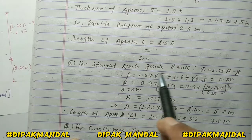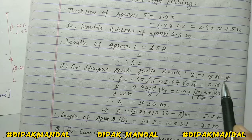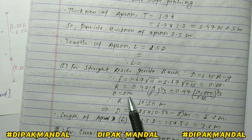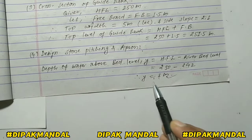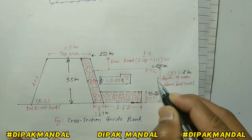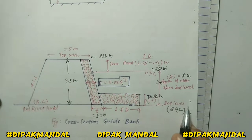So for the straight Guide bank, we have to use this formula, D equal to 1.25 (R minus y). Okay, and the value of y is already known, that is 8 meter. We have already calculated the value of y equal to 8 meter. So you have to show this value also in the figure. So this value is 8 meter. Okay, so simply say this is the 8 meter, that is the depth of water above the bed level.